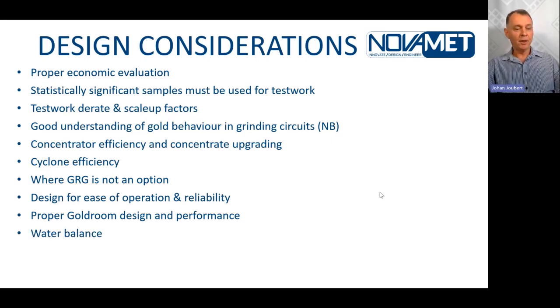Then the water balance. You would fall on your back when you see the amount of water these concentrators add to the grinding circuit, and actually the whole circuit by itself. You have to do a proper and detailed water balance to make sure you do not affect your milling circuit and the downstream with all this additional water that you're adding. If you're installing a lot of concentrators, you will be required to install additional equipment to do any density corrections.